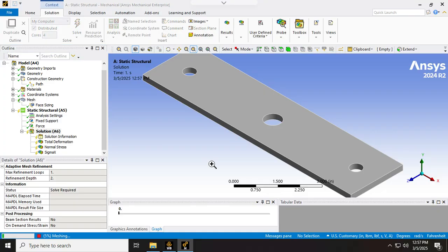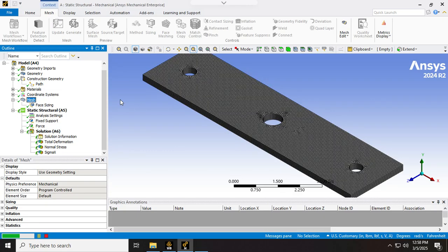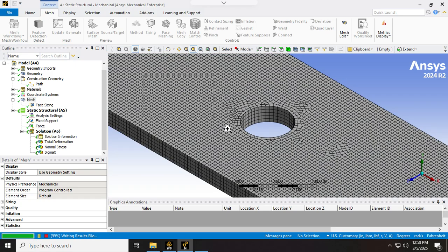You know, how refined the mesh is gonna get. It's gonna uniformly refine everywhere. I wanna see how much effect it's gonna have on the results. Technically, refinement around the hole matters the most. Alright, so it's working harder now because we have a lot of mesh. Yeah, you see the mesh. But the good thing now is it's uniform. So if I box zoom in, it's more uniform.